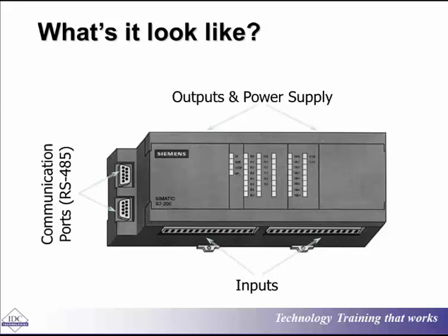This is a small PLC, and there are many different larger types, but they basically start off with what could be referred to as a shoebox PLC, in that the processor and the input and output interface are all on the one plane. It also has the communications as well. This is considered a small PLC, with a fixed inputs and outputs ratio, and also a fixed input and output maximum number.